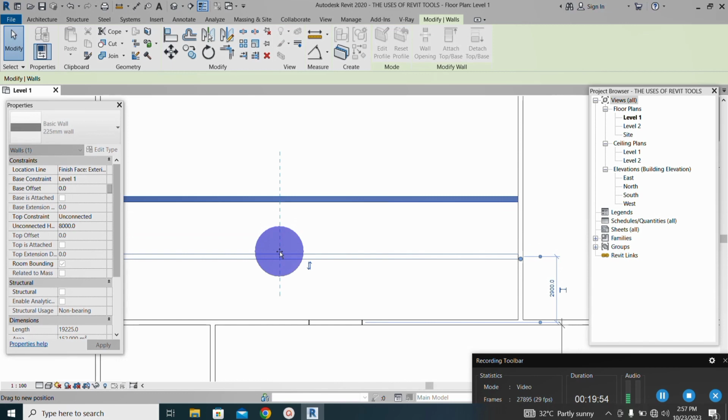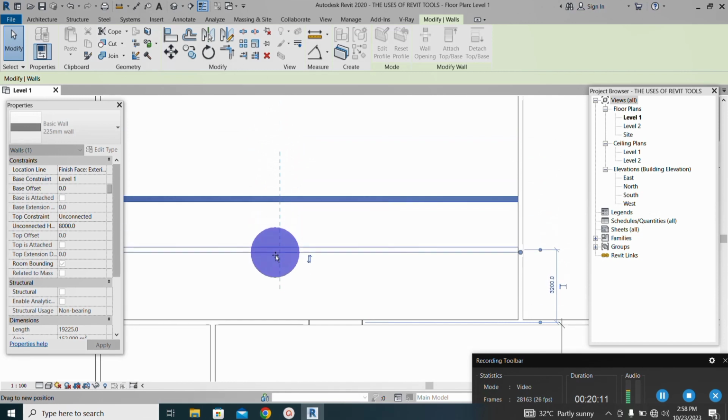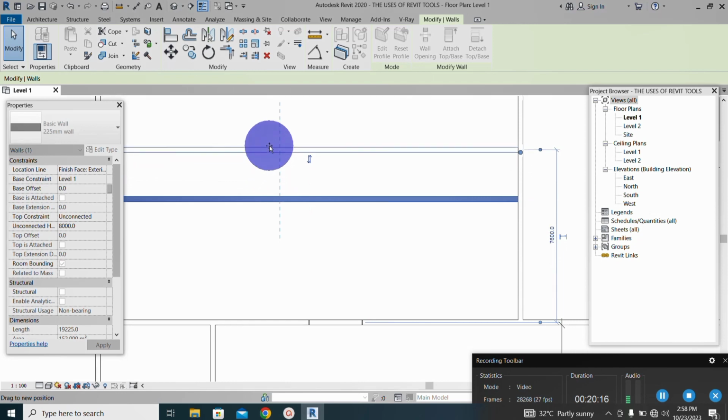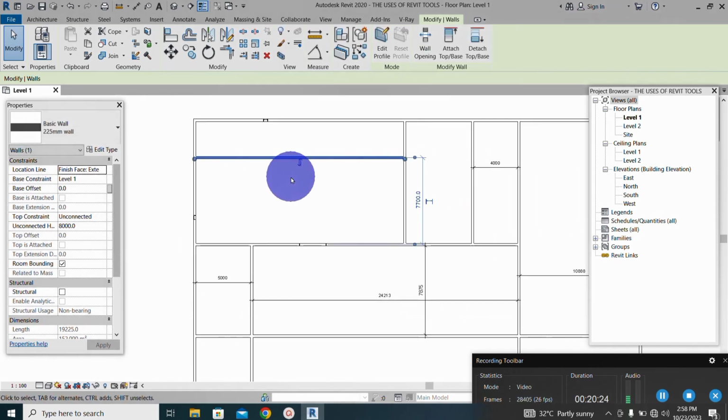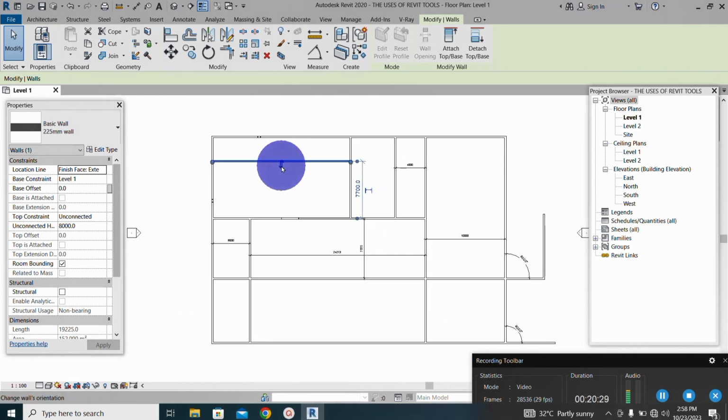You can see this has shown the command. If you look at the command, they are similar. Look at the command on my cursor. You can see that it's the same thing with the move to. You can only be looking at the dimension that is coming out. When you get to a specific dimension or your desired dimension, then you left click on your mouse. That is the other way you can use your move tool.